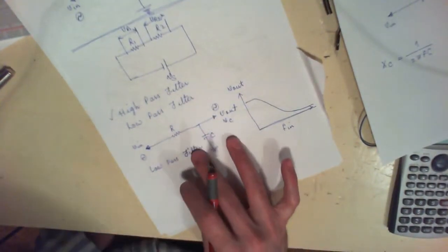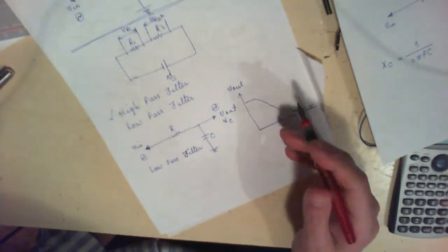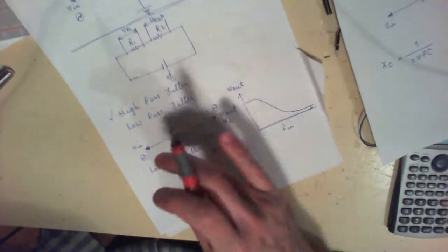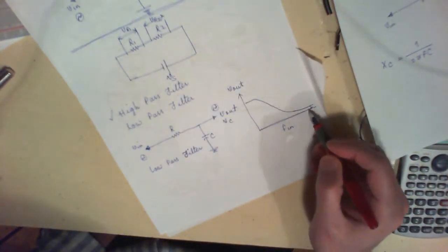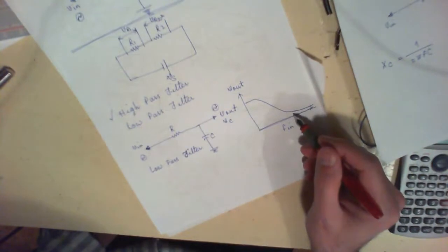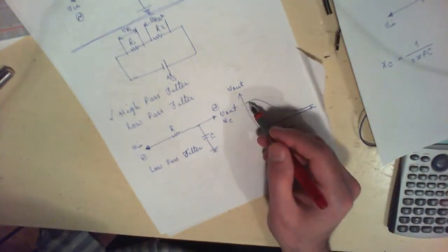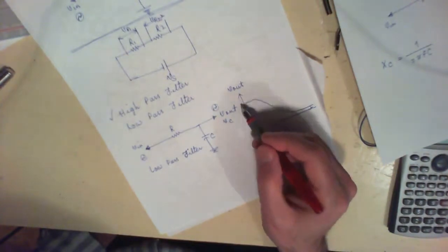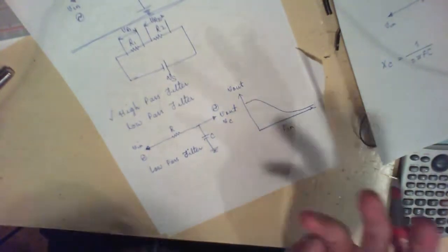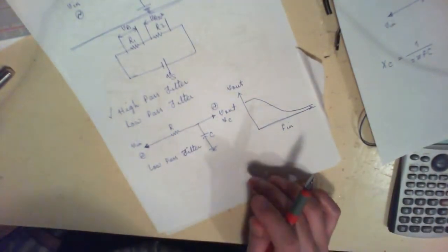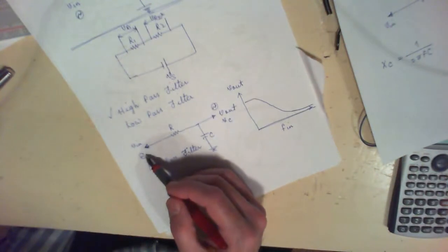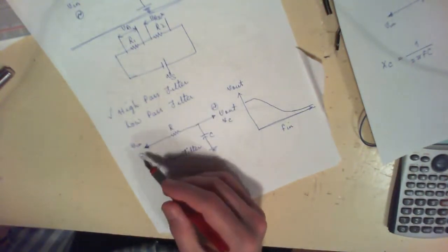So this low pass filter over here has been called a low pass filter because, as you can see, at very low frequencies most of your signal is passing through, and then at high frequencies most of your signal is being suppressed and not really passing through the filter. Meaning that over here the output voltage is very close to the supply voltage, and over here the output voltage is very close to the ground. So that's basically why it's called a low pass filter. And of course, you know that you can control this voltage with the frequency that you're providing to the circuit.